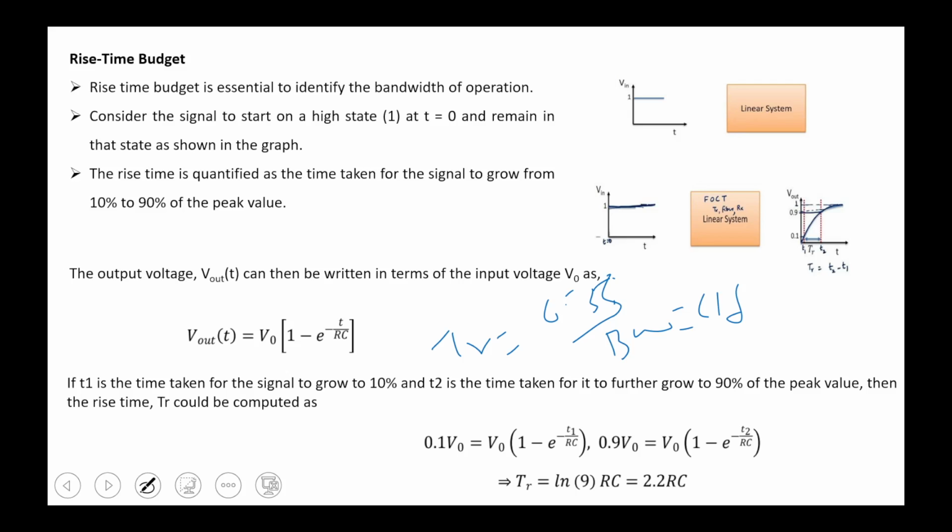Yes, Manish. So how can you relate the rise time in both cases? Rise time in case of non-return to zero, the bandwidth is B by 2, so it will become 0.7 divided by bandwidth, and for return to zero it will remain the same, 0.35 divided by bandwidth. Okay, good. Good, Manish. Thank you.